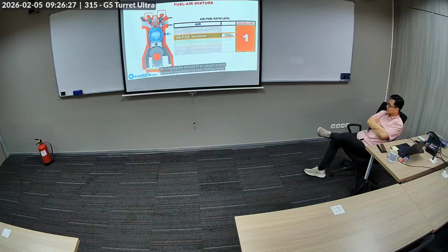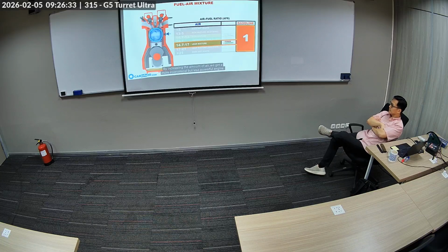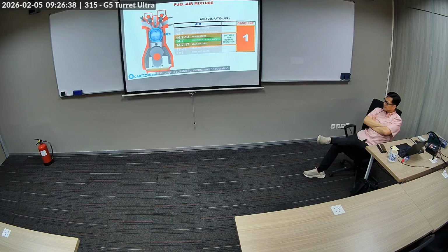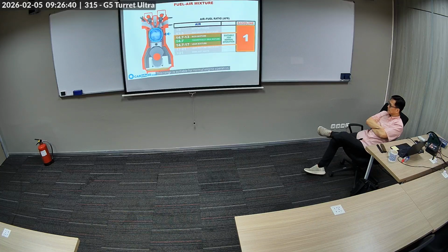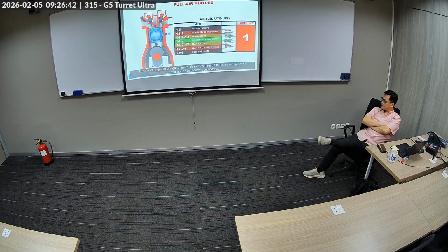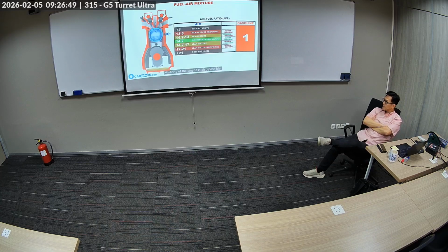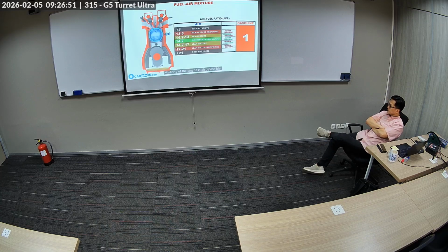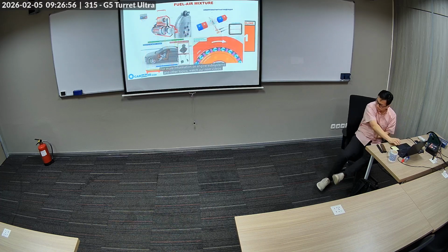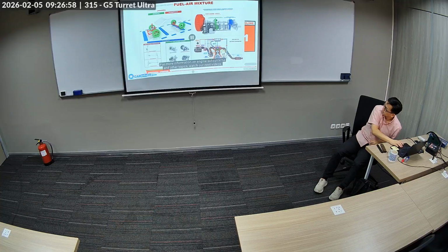By reducing the amount of air, we get a more powerful engine but a poorer fuel economy. By increasing the amount of air, we get a more economical but less powerful engine. This range is suitable for normal engine operation. Further changes in the gasoline-to-air ratio will result in increased gasoline consumption and decreased power. Misfiring of the engine is also possible. This concludes our review. For more information on engine subsystems and other topics, watch our next.